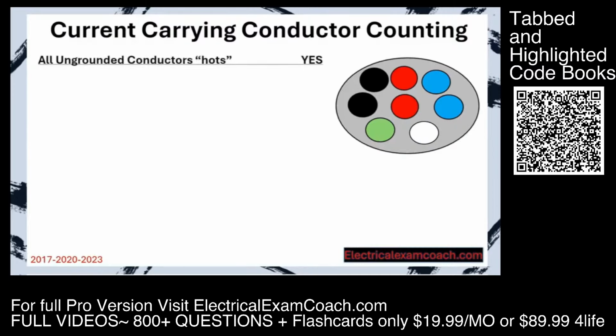The first one's easy. All ungrounded conductors. All of the hots are going to be considered current carrying conductors under normal circumstances. The second one is the neutral of a line to neutral load, meaning if we have a light bulb and it draws 1 amp on a 120 volt circuit, there's going to be 1 amp going in on the hot and there's going to be 1 amp flowing back on the neutral. So it is as well a current carrying conductor.